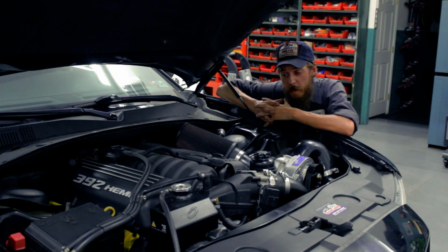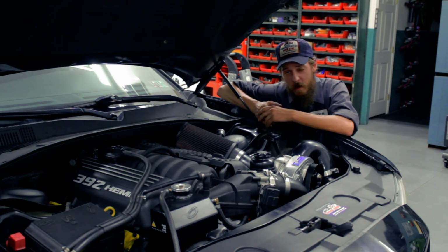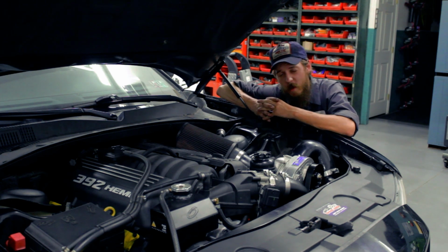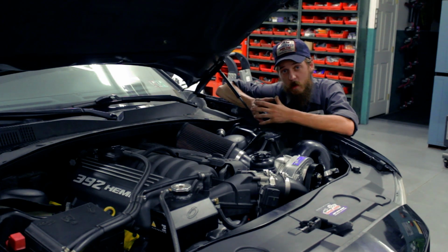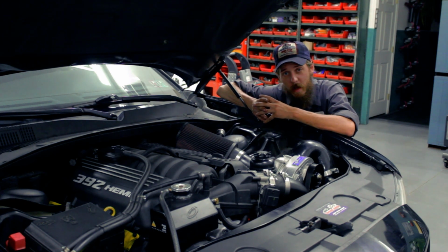So what we actually narrowed this particular no crank down to was a failed transmission temperature sensor. One that wasn't fully failed. In fact, it was reading temperature within the range that we would expect it to, but the interlocks weren't working properly. Essentially, when it should be seeing full system voltage, it was maintaining at temperature sensor reading voltage, which was a fault within the transmission. Unfortunately, I'm not going to be the one tearing into this transmission to figure out exactly why that happened, but we've narrowed down the fault to there, and they can take it from there.